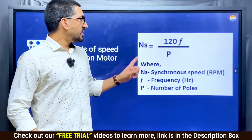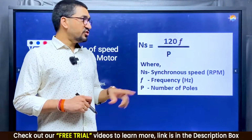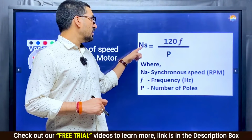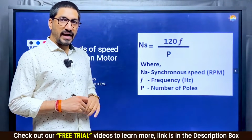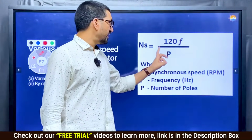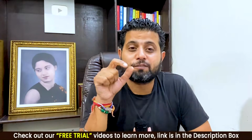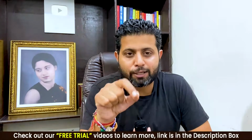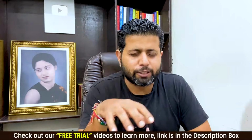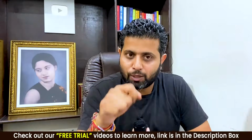That means there are basically two ways we can change this rotating speed of RMF and then the motor: we either change frequency or change the number of poles. Induction motor speed control is done with variable frequency drive, and I guess that is why you're watching this video. Very important. In a lot of shipping companies' interviews, these questions have been asked. So I hope you like it.